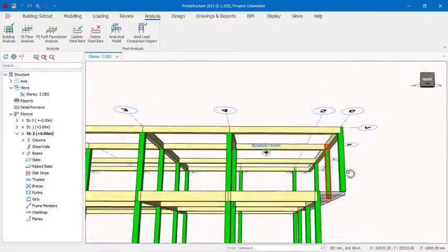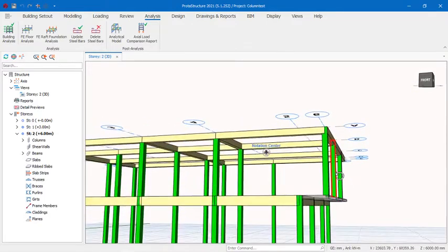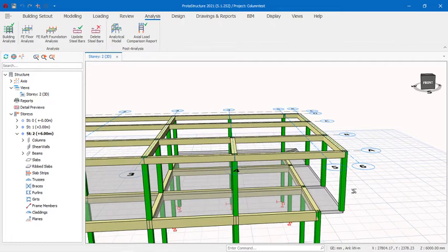In any case, some people put the beams in while they are running the analysis. Once they are done with the analysis and they are okay with the result, by the time they are exporting their model for detailing, they will remove all those beams that they put there. So which also works in a way anyway.